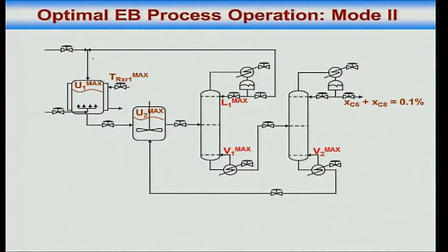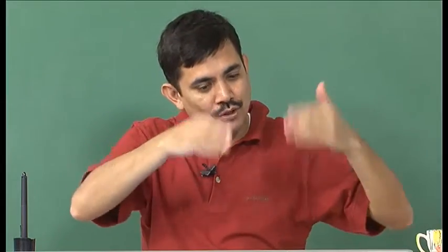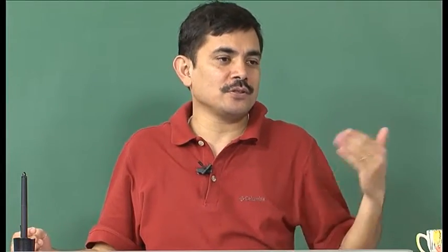At maximum throughput, these constraints are active. Earlier throughput was given. Now FC2 itself is a decision variable. Earlier FC2 was fixed, and the other 8 variables were optimized. So if it's maximum, then... we don't know what that maximum is. You are maximizing FC2, but FC2 itself is a degree of freedom that's used up because it's not specified. It is free to float.